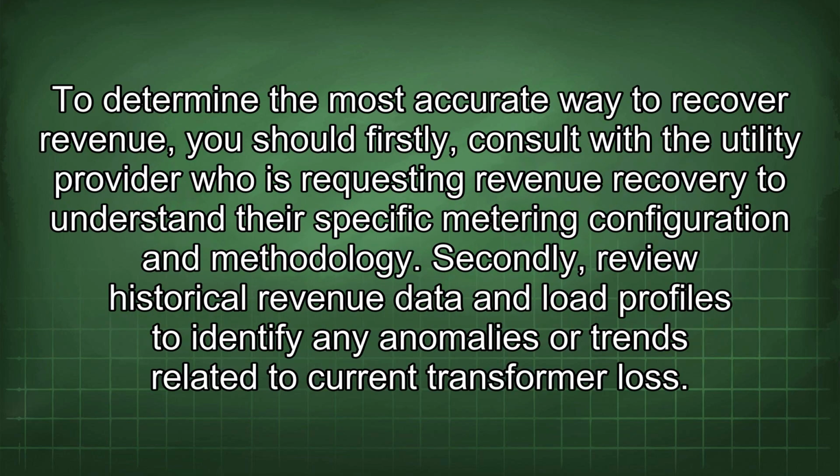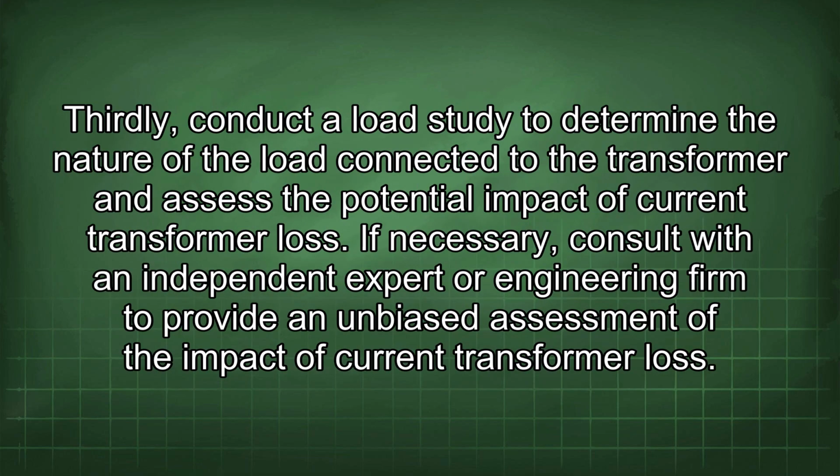To determine the most accurate way to recover revenue, you should firstly consult with the utility provider who is requesting revenue recovery to understand their specific metering configuration and methodology. Secondly, review historical revenue data and load profiles to identify any anomalies or trends related to current transformer loss. Thirdly, conduct a load study to determine the nature of the load connected to the transformer and assess the potential impact of current transformer loss.